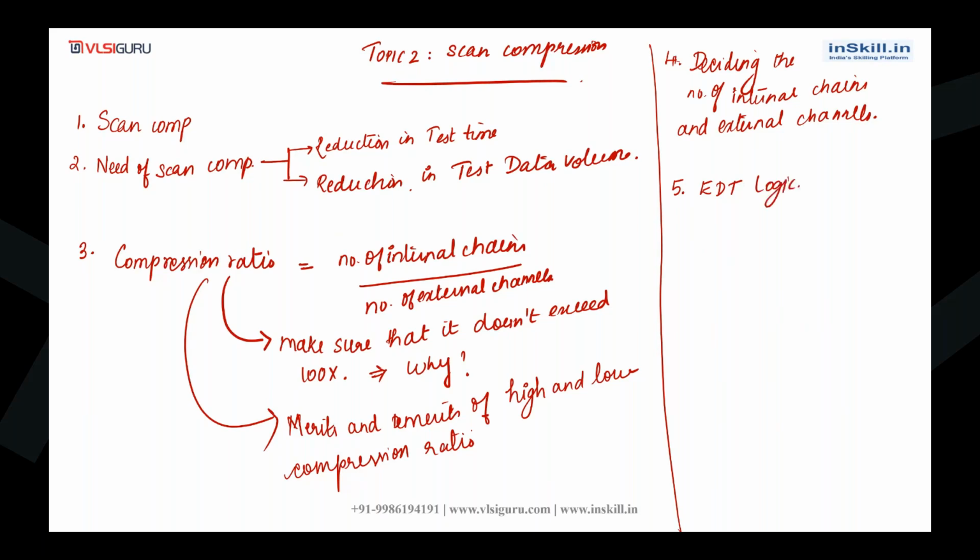So as I told, if you want to go for scan compression, if you're using Mentor Graphics tools, then you need to add a logic called the EDT logic. Inside the EDT logic, you'll be having these four components. The first one is the decompressor.